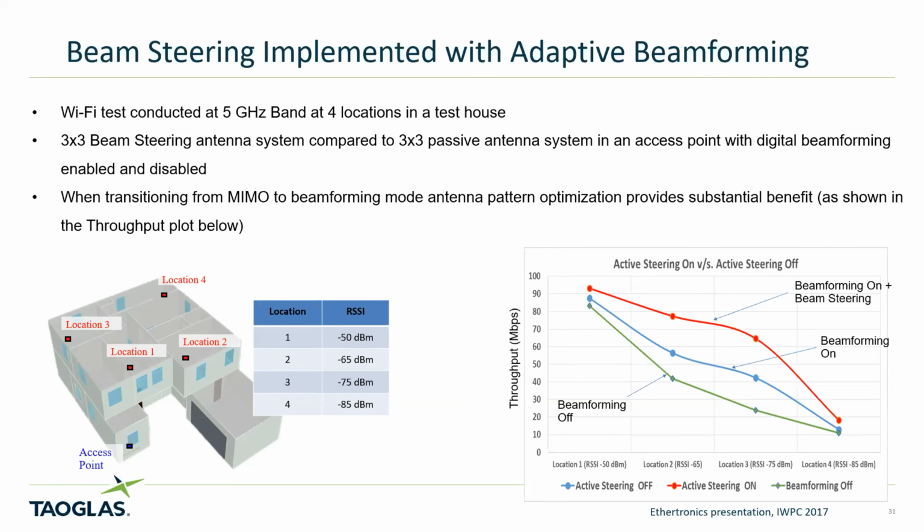There it's a different problem, but the tools they have at hand is, instead of looking at these 2, 3, 5, 7 dBi, they'll actually put in a reflector, a high gain reflector, or they could put in a phased array. They'll drive up much higher gain values on both ends of that link. So that's where you will see 20, 25, even 28 to 30 dBi of gain on one or both ends